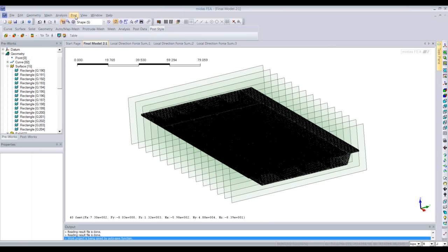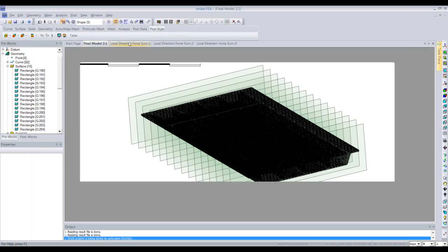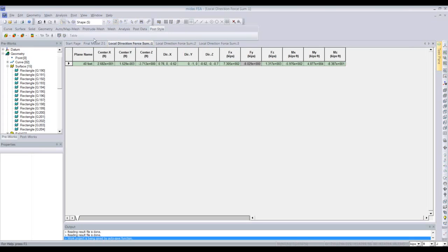The code asks you to calculate the moment of resistance. It asks you to calculate the shear force, etc. at different locations, and then you can obtain the moment of resistance and compare it with the design bending moment, shear force diagram, etc. And this way you can check everything.